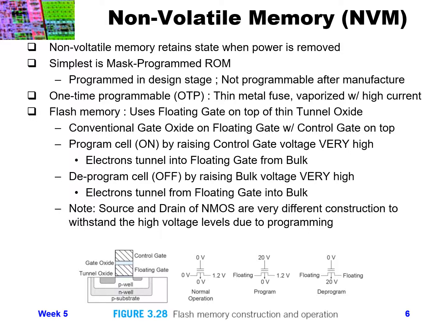So this floating gate is now at a certain charge even when the control gate goes back to ground. And that charge will cause the channel to be either on or off. So when you program the cell, you pull charge into the floating gate, and then that floating gate will cause the channel to be charged and to be on all the time, even when the control gate voltage goes away.